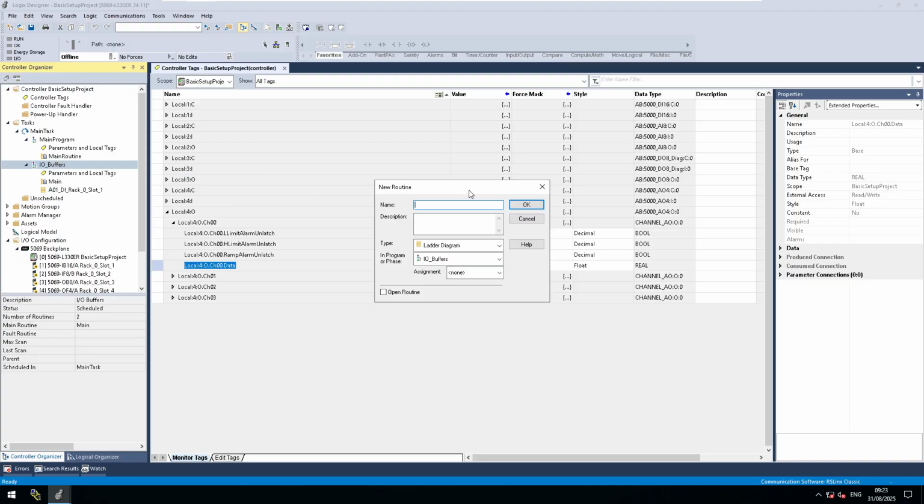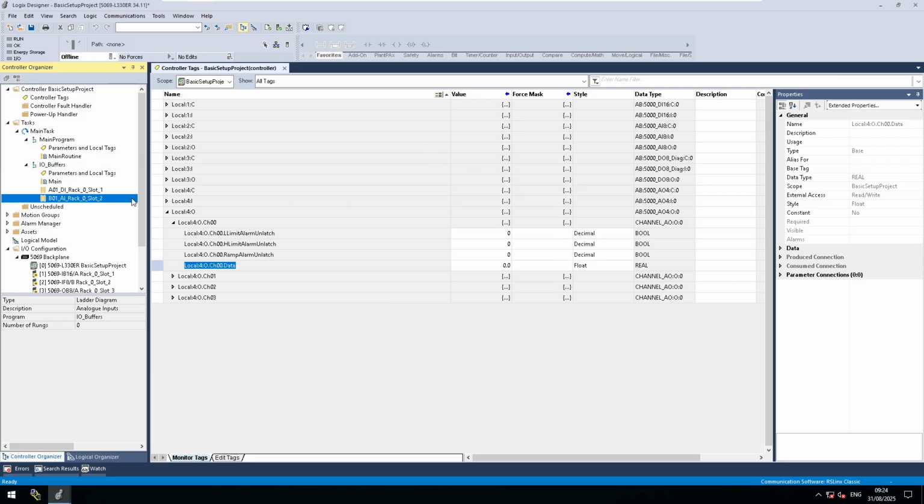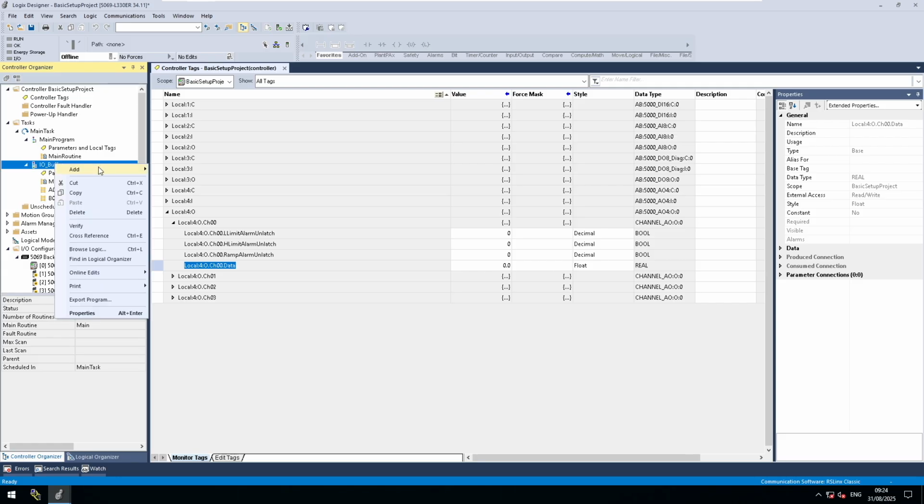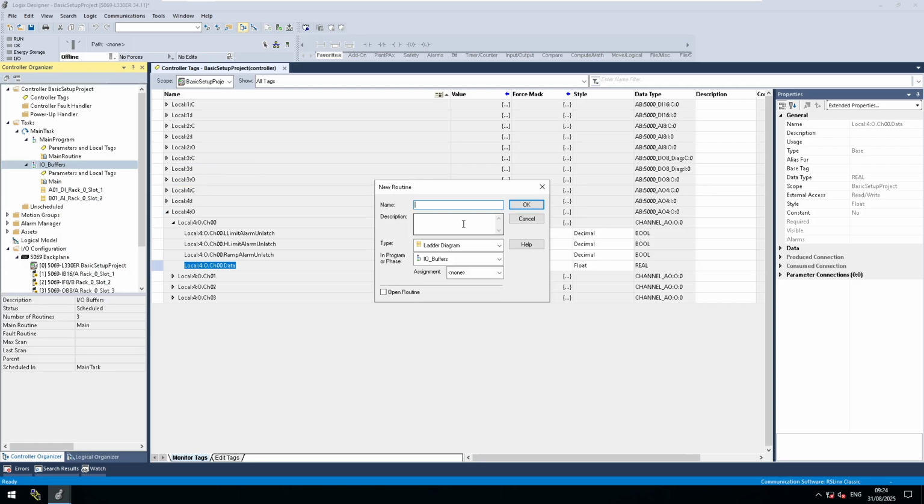Going to add a new routine now for our second card, which is our analog input card. So I'm going to call it B01. I usually go up in A. So if I had another digital input card, for example, that followed on from the last one, I'd have A02. So then it just keeps everything ordered nicely. But because this is different, it's not a digital, it's an analog, I'm going to go on to B, call it B01. You can reorder these in the program itself, but I just like to have them so I know that it's always going to be in the correct order.